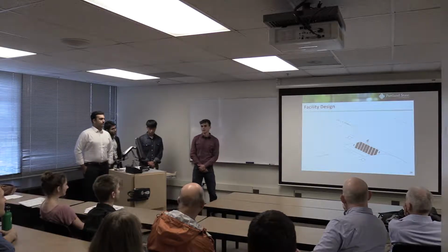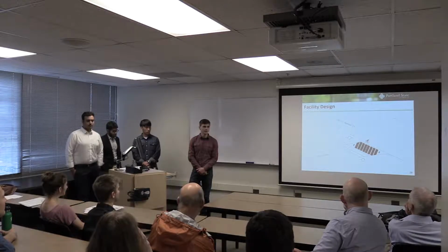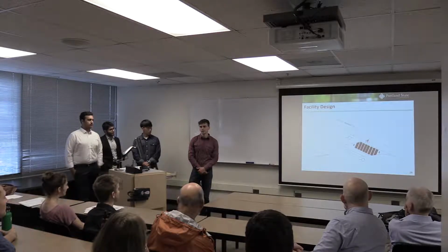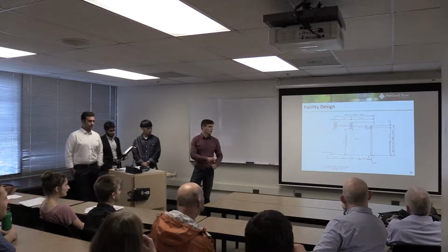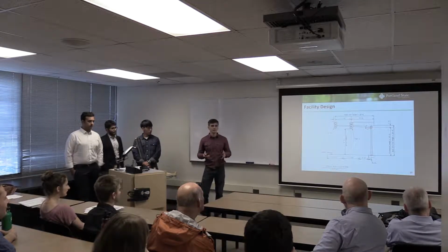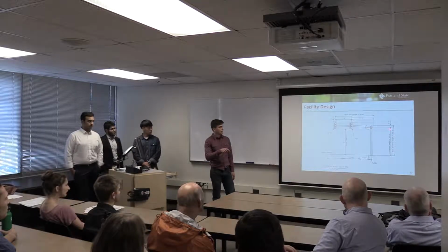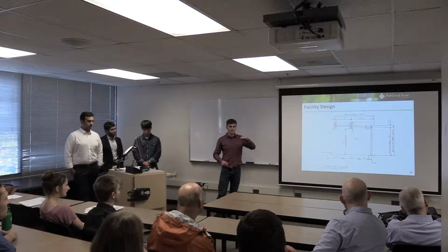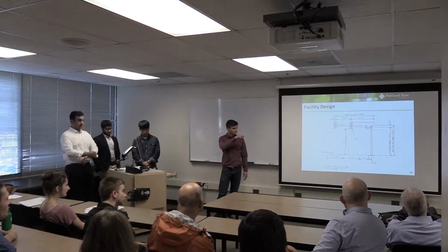So I'm going to discuss our design aspects, specifications, and guidelines for this project. For our first signal, we referenced the design manual by ODOT for signal design. We're going to construct a steel mast arm. The pole length is going to be 20.5 feet, and the mast arm is going to be 19.5 feet from the base of the pole up.